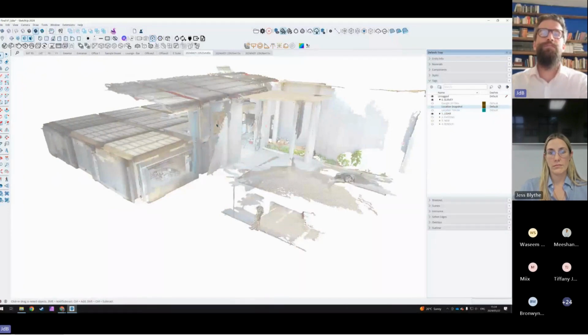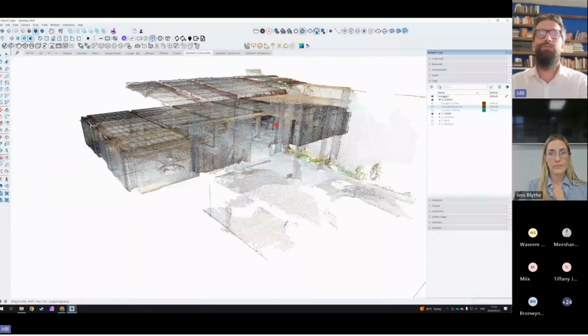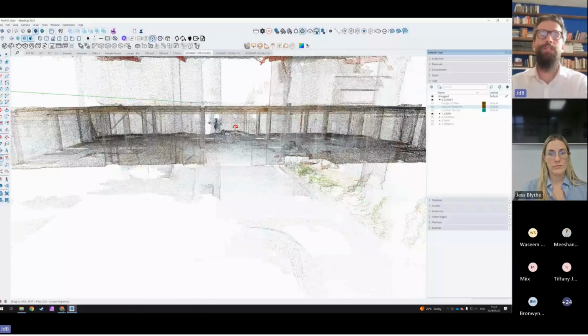And then we can intensify that visibility. We can basically change the opacity to 75% blending. And if that is not enough, then conditional blending allows us to see everything 100% saturated if there's no SketchUp object drawn there. So here we can see really roughly the entrance area, and when we zoom in, we can walk into the space to see those concrete columns.